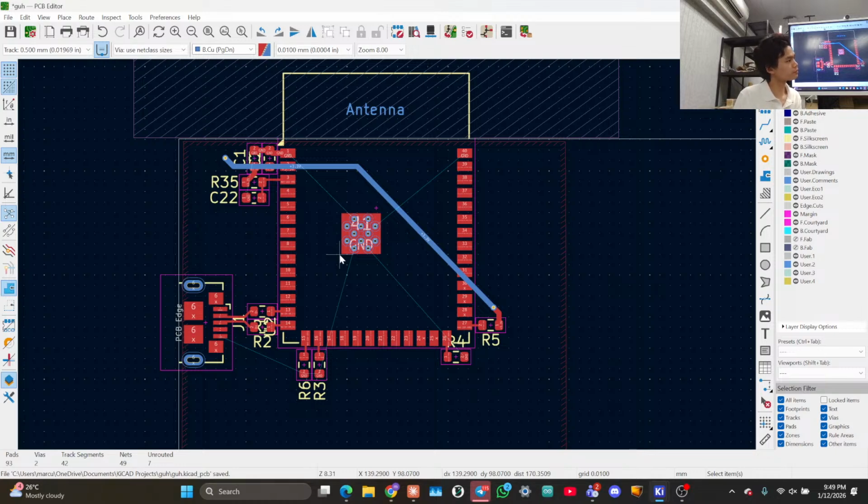Okay. Yeah, but I was thinking, shouldn't there be software that you just highlight the whole thing, click a button, and then it automatically does it? Yes, but impedance management at high frequency is a nightmare, and the software problem is insane. So nobody has done that. You can auto route something like this with software and it'll work, but the moment you have high frequency, it's over.